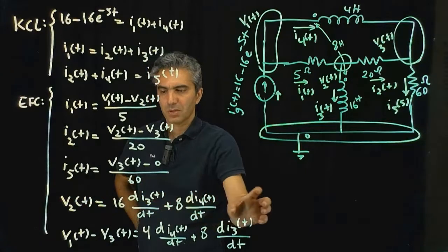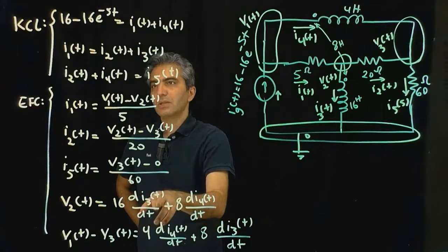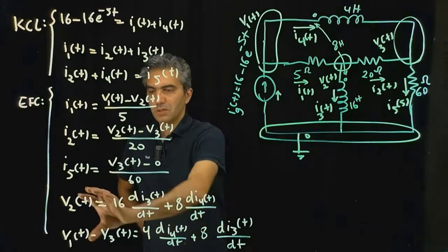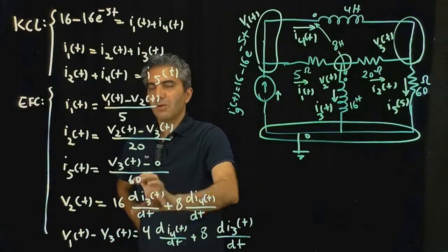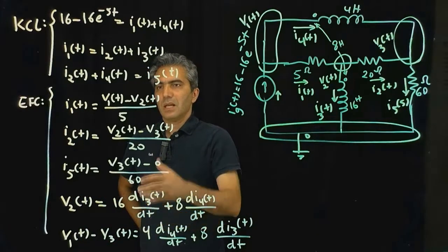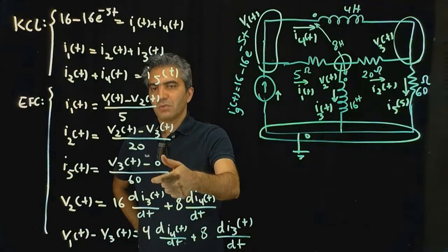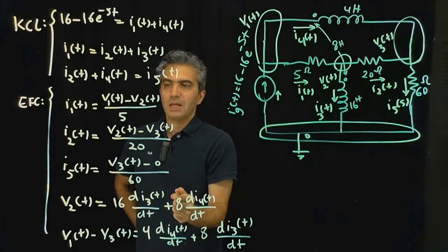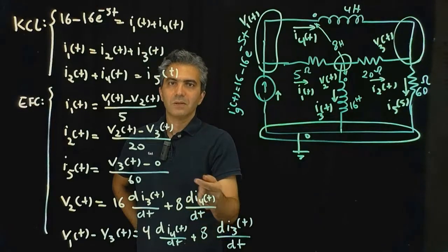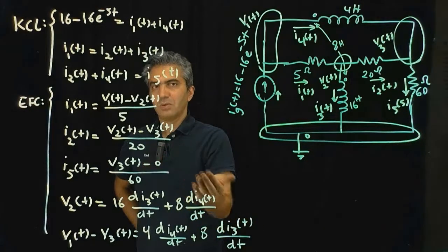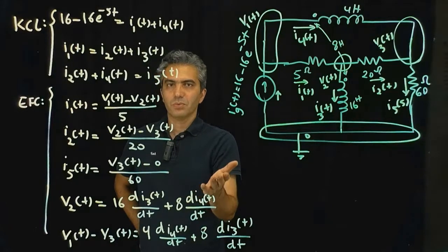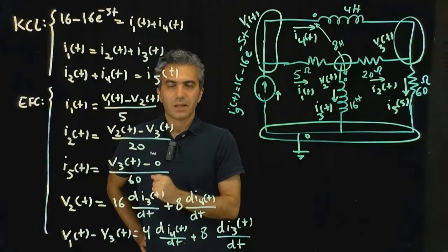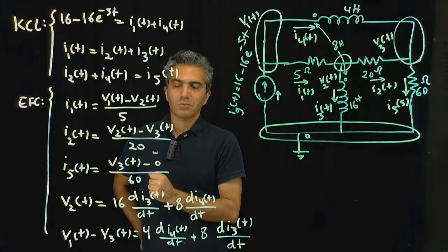So this turns into an equation that only has voltages. I can do the same thing for I3, and then once I do that to these two equations, I end up getting equations that are only a function of voltages. And with that, I reduce the number of unknowns from 8 quickly down to 3, only voltages. And once I have that, I can reduce the number of unknowns or equations from 3 down to 2 and 1, and finally get that one differential equation that could be solved.